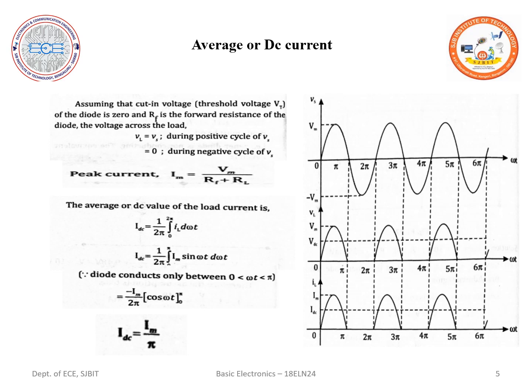Looking at the waveform, for one cycle of the input, which varies from 0 to 2 pi, during the positive half cycle the input, whether in terms of voltage or current, gets converted into DC. But for the negative input voltage, my output is 0, whether in terms of current or voltage. Looking at this waveform, let us derive the expression for the average DC current.